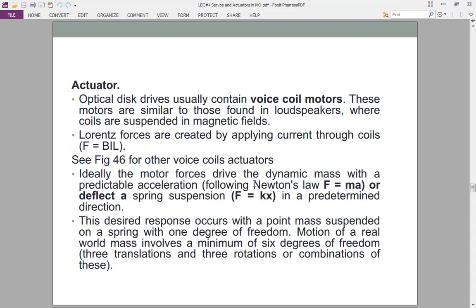If it is positioned vertically, then of course it is likely to cause more errors because the focusing and tracking servos depend on the position of the objective lens. That's why it's better when the objective lens is positioned so that gravity is the only force acting on it downwards. Okay, I think that will be explained a bit later.